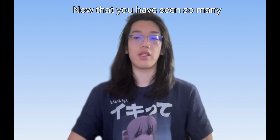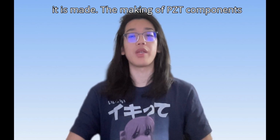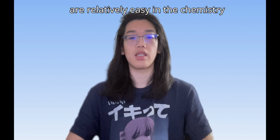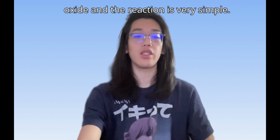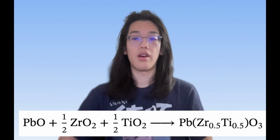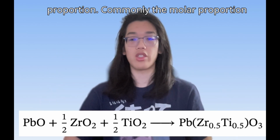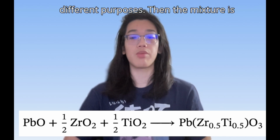Now that you have seen so many applications of PZT, you may wonder how it is made. The making of PZT components and other similarly structured perovskites is relatively easy in the chemistry part. The raw materials are just metal oxides, and the reaction is very simple. First, they are weighed in stoichiometric proportion. Commonly, the molar proportion is 1:1 between zirconium and titanium, but there are variations for different purposes.